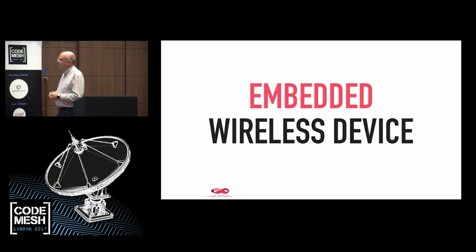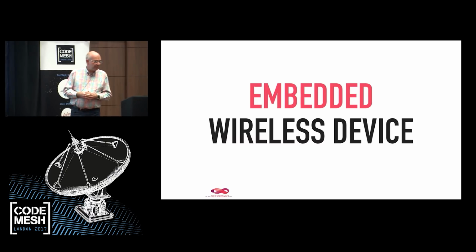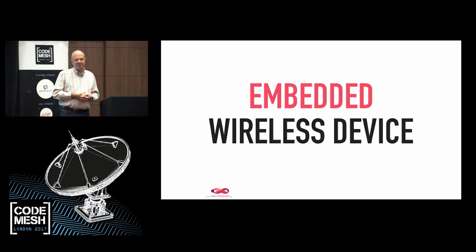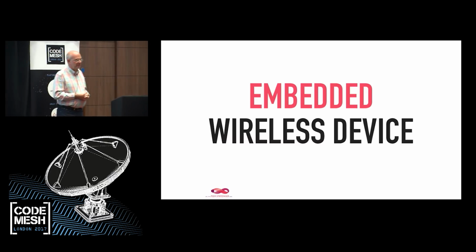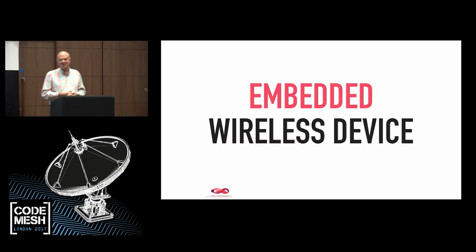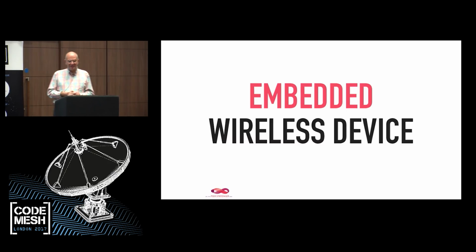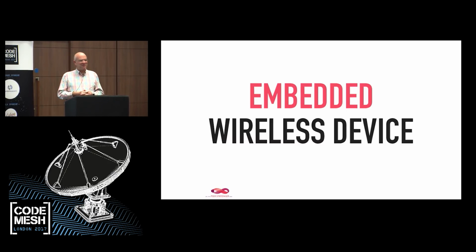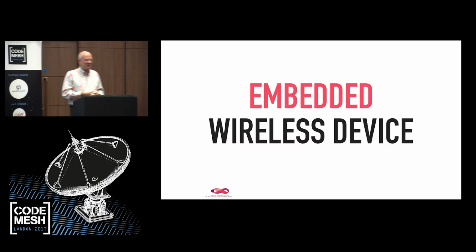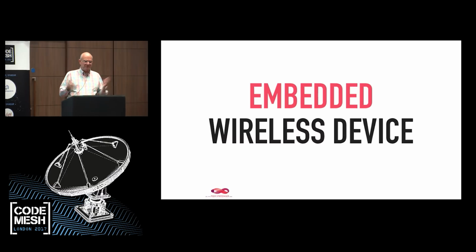So the thing is an embedded wireless device. It has Wi-Fi on it. We decided Ethernet is kind of boring, let's put Wi-Fi on. I can tell you we paid dearly for that. This is the main cause for the one-year delay, the Wi-Fi thing. And actually not the antenna, that was only a few weeks, but USB on the main chip was broken, and so we had to work around that.